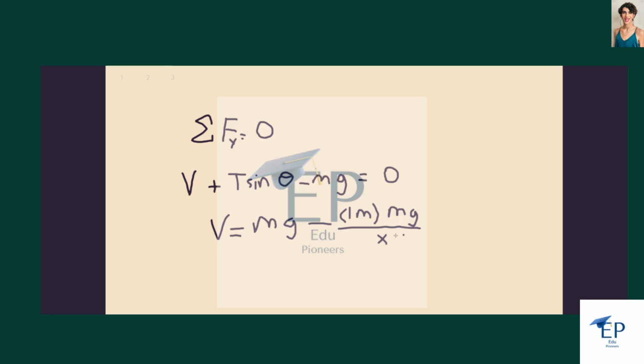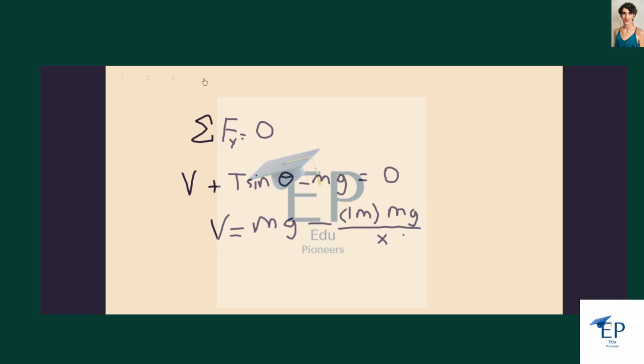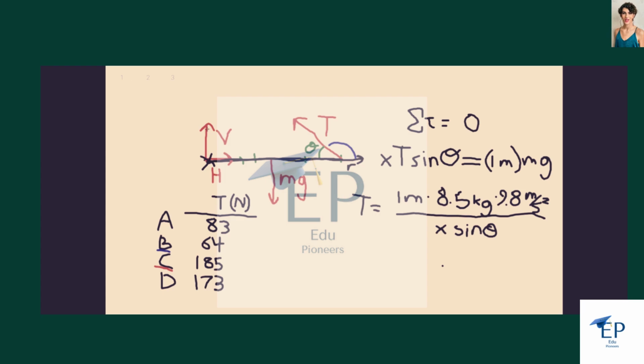In cases C and D, if we plug in x here, we're going to get a negative value for V, which just means the force has the same magnitude as the absolute value of that negative value, but it's actually pointing in the downward direction. And that's fine. When originally drawing the free body diagram, we just guessed that the vertical force is pointing up because its actual direction is going to depend on the relative magnitude of the weight and the vertical component of tension.